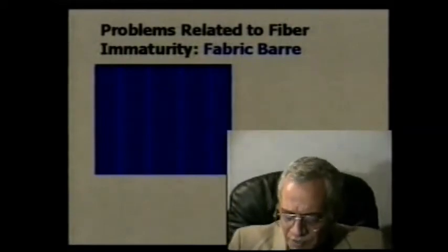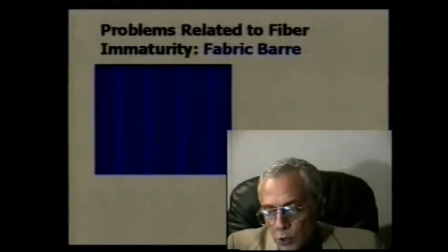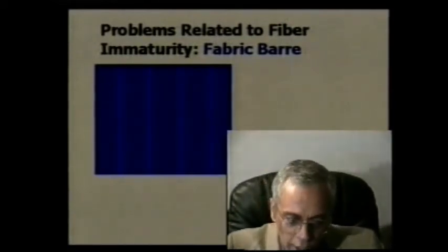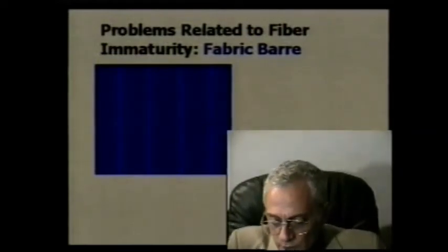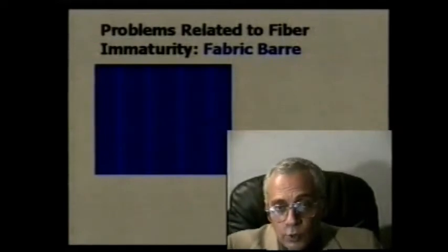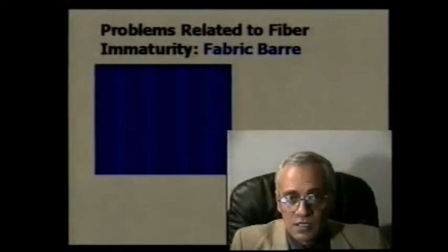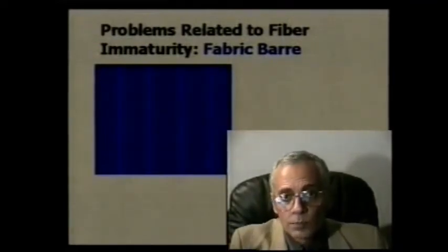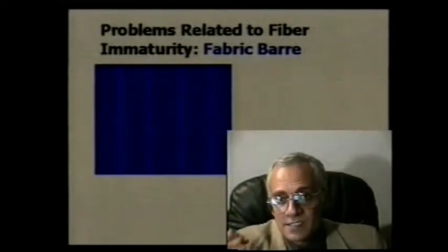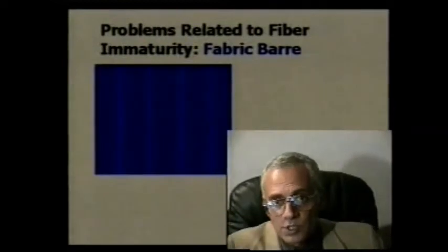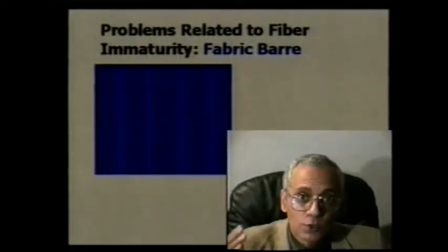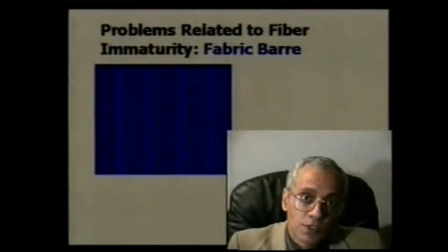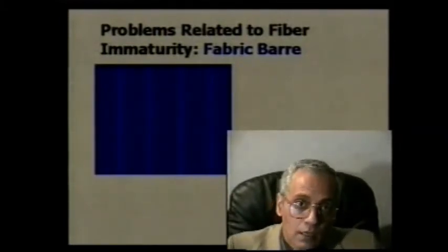There are many factors that can contribute to barré, including variation in the mix, in the fineness, on the micronaire, on the color. You want to watch out for the consistency in the micronaire, and more importantly, in some cases, the consistency in the color. If you allow, for example, the yellowness of the fiber, the +b, to swing high and low, then you're more than likely getting yourself into a major barré problem.